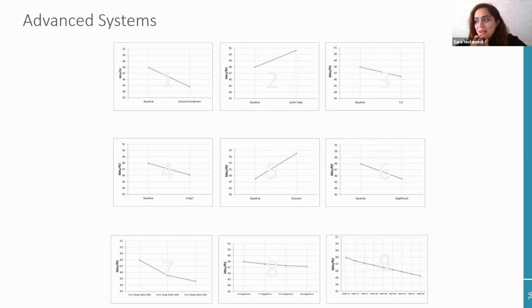Yeah, I already knew that San Francisco is just mild and Chicago is just harsh, so the impact is going to be higher, but I never really thought that the envelope really matters in Chicago but maybe not that much here. You can have all glazing here and not see that much of a difference. You can offset that by putting some PV panels up there. Yep, you are just dealing with different climates.